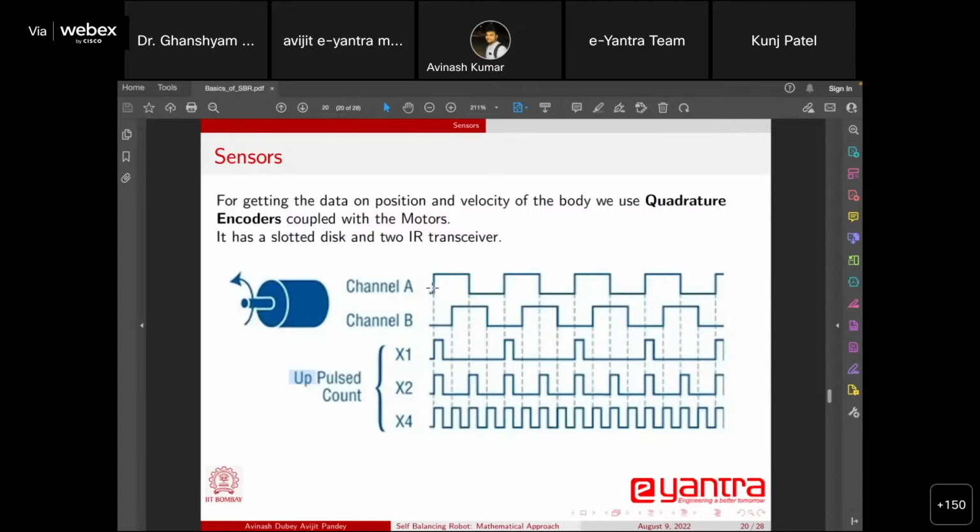If a slot is passing through A, it will not immediately pass through B. It will start entering the area of the second sensor after it is halfway through A. So what it gives us is a set of two pulses, and combining them, we can have multiple observations for one particular slot pass.